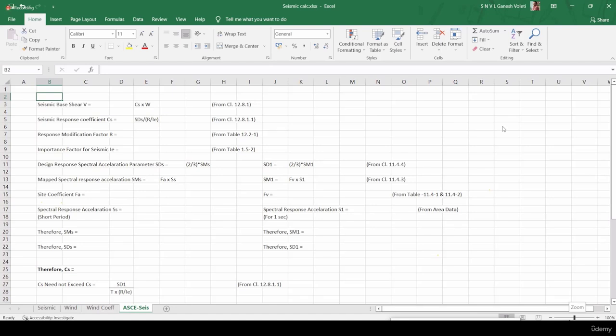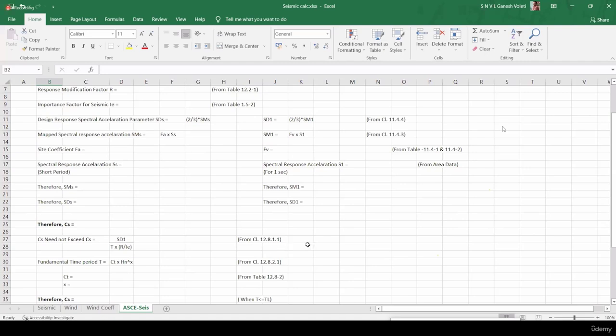But sir, actually in Rajasthan, some people want to get it vetted by authorities. So what is the remedy? They will not accept AISC. Actually, they want it in IS 800. This is our problem. We face it two times. You can do it in IS 800, damn sure, but you'll get a slightly uneconomical section. There is no problem in that. Slightly, not much change. Probably you'll get around 10%. If you do much more optimization, you get around that. This is my suggestion, only one suggestion.